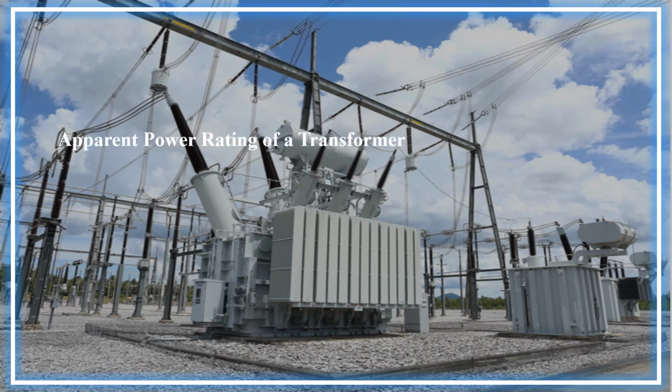Next is apparent power rating of a transformer. The primary purpose of the apparent power of the transformer is to set the current flows through the transformer windings. The heating of the transformer coils depends on the current flow through it. The apparent power rating of the transformer has to account for the nature of the load since loads are not purely resistive.